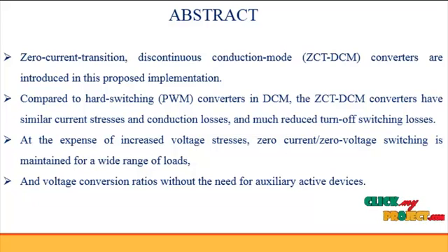In AC to DC applications, high power factor is obtained automatically without the need for active control over the input current. In order to realize the zero current transition condition, the auxiliary circuit consists of a coupled inductor, a capacitor and an auxiliary switch, which also operates with a zero current transition condition. Moreover, the coupled inductor plays an effective role in achieving soft switching conditions.